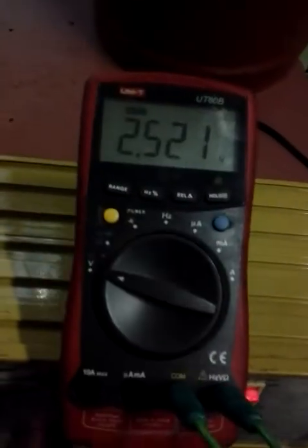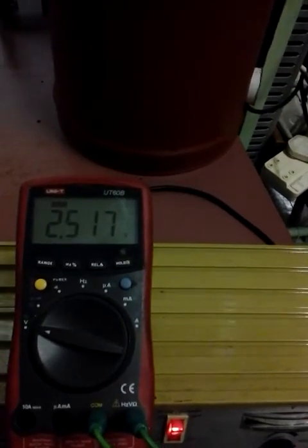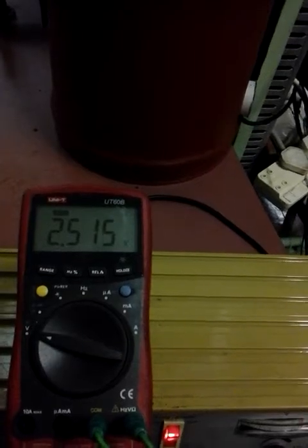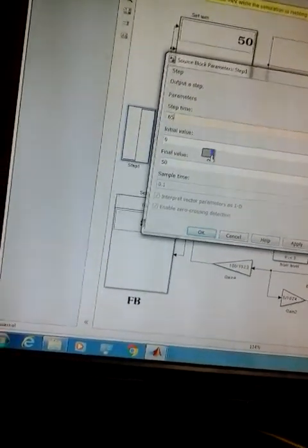Okay. Let me check the next point. What else we need? Measure and record. That's what we were doing. So I was measuring. First, we had to do some calculations using that simple maths. Then I'm measuring the output from the sensor, and this is your signal output from the multimeter. So if I change the set point to, let's say, 70, or let's put 65,